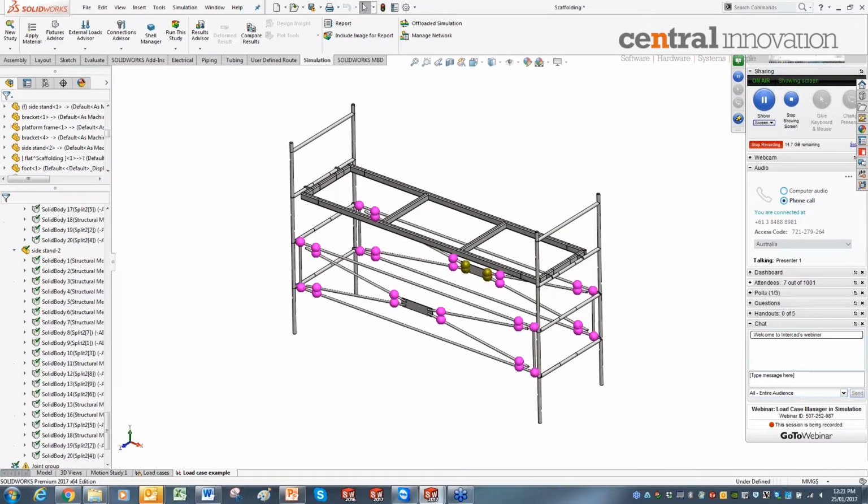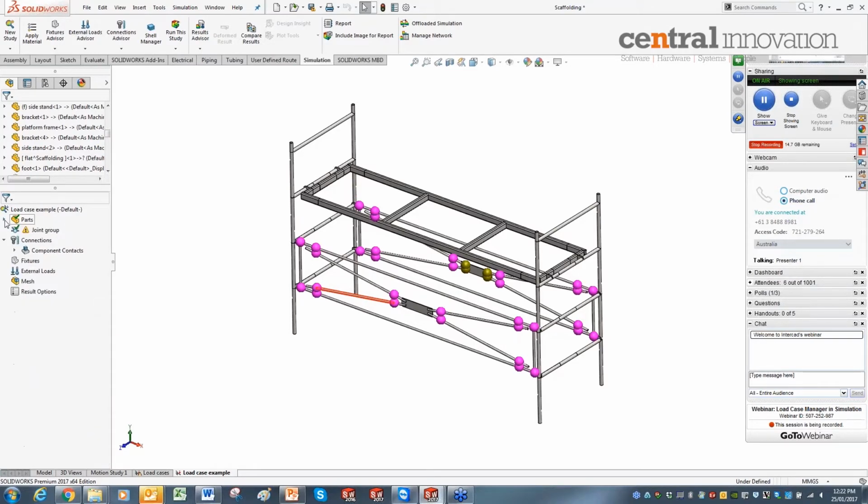Okay. So in case you want to copy any material properties, you can simply right click, copy the folder and paste it into your new study. You can see here, my beam element is transferred. These are the icons for the beam element, and this is an icon for the solid element. And this plate I'm treating as a solid, and some of the beams, for example these tubes, are treated as a beam element.